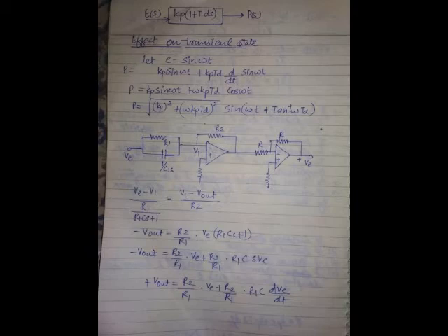What is the effect of this controller on peak overshoot? It decreases. Peak overshoot is decreasing, which means zeta is increasing: it increases damping ratio and hence reduces peak overshoot. Next.